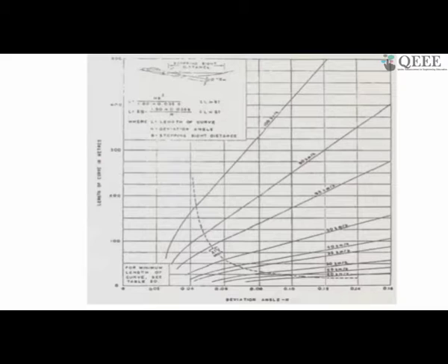From the vehicle point of view, the valley curve is not increasing the effort at the time of going downhill. It is only after negotiating the valley curve, when it is coming out of the valley curve, and if it is an ascending gradient, that's a summit curve. When it is going towards the summit curve, actually the effort is increased. So once the vehicle negotiates the summit curve, then it is actually eased out.